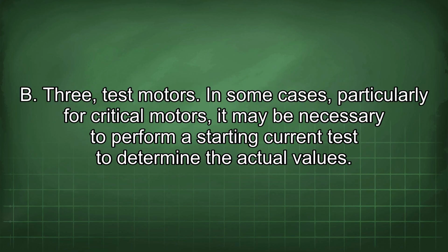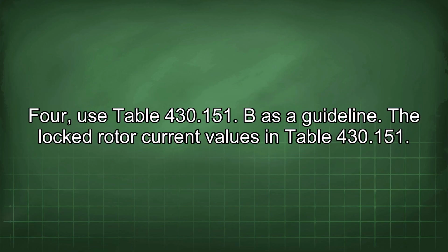430.151(B). 3. Test motors. In some cases, particularly for critical motors, it may be necessary to perform a starting current test to determine the actual values. 4. Use Table 430.151(B) as a guideline.